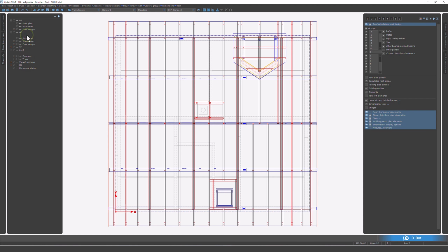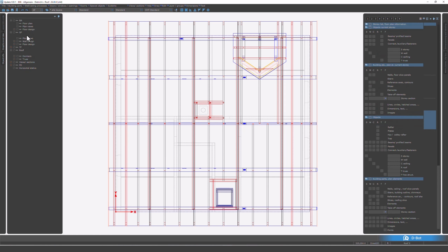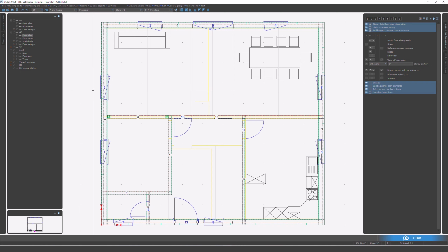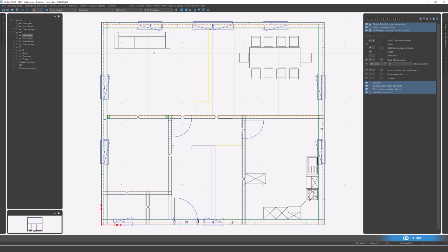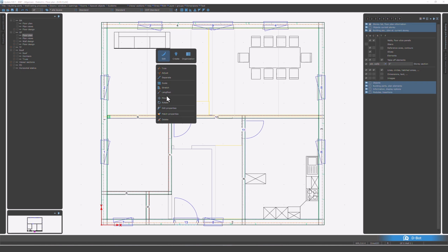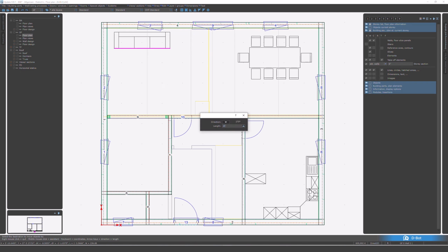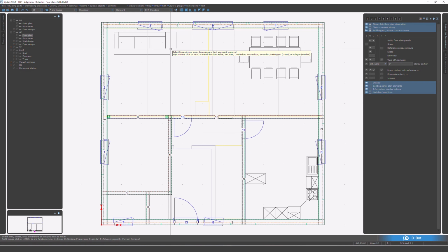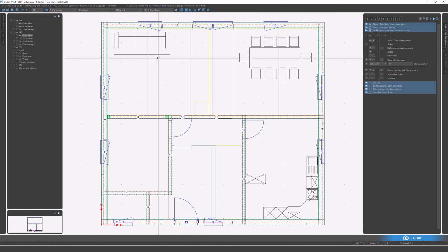I'm going to change back to the floor plan now, and I'm going to show you another type of contextual menu, which is the list of the last used commands. In order for me to illustrate the other type of contextual menu, I'm going to first go up here and move this line. Just going to move it down a foot. Then I'm going to use the plus sign. I can choose that now and move this item over 1 foot. So that's exactly as it's been before.